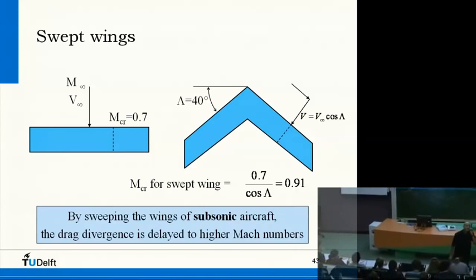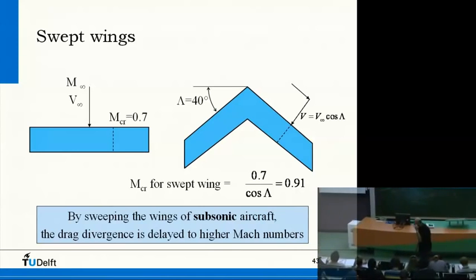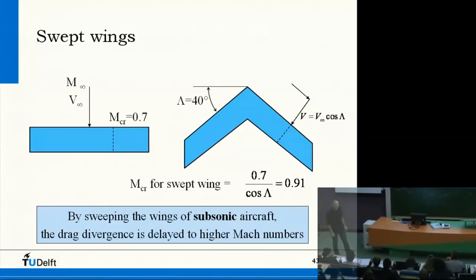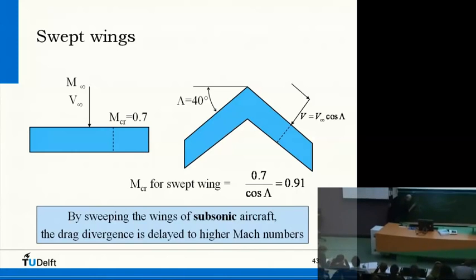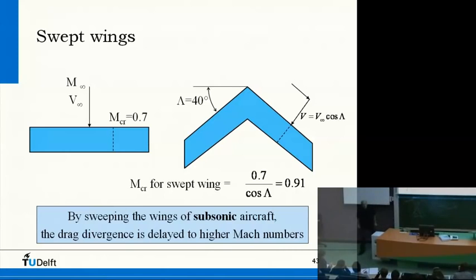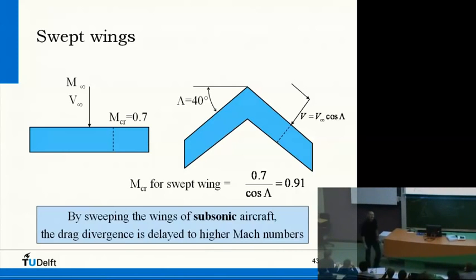The benefit of a delta wing is the fact that it has a large vortex, which creates a lot of lift, because the velocities here are high and the pressures are low.